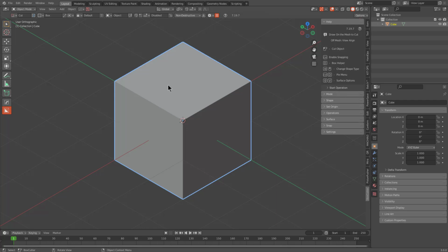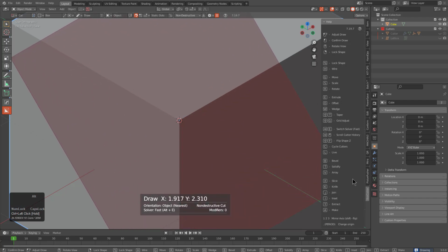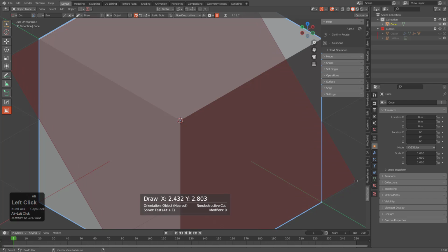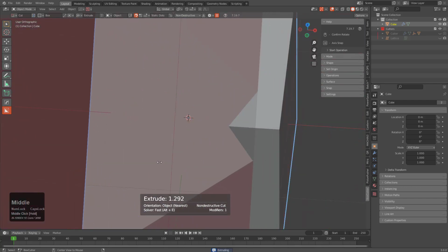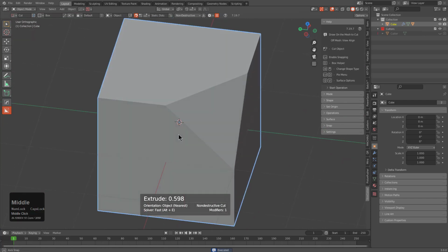So there's this test called Work to Corner that's an alignment test of sorts where basically users will activate snapping, which will give them dots, and then inside the snap panel activate static dots, which will give them static dots. This means that when you hover over a dot and you roll the wheel twice, you're able to look at alternative alignment points, giving us this basic shape. So after creating this shape and performing our first cut, we are now basically working the corner.